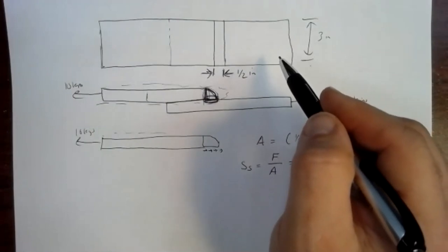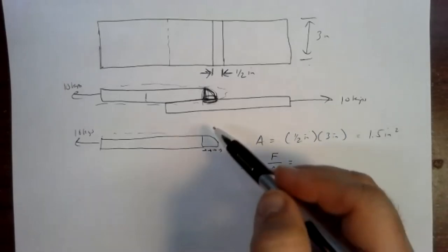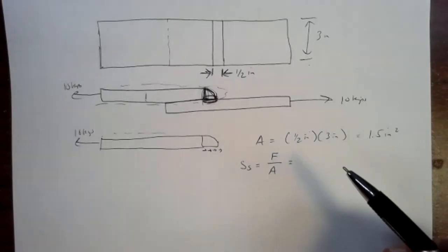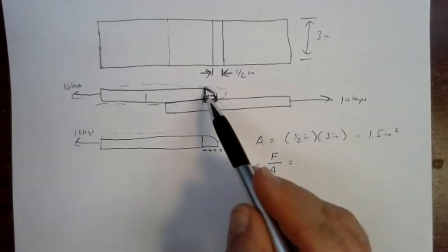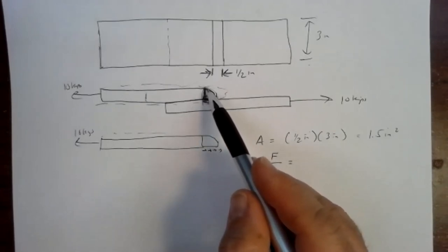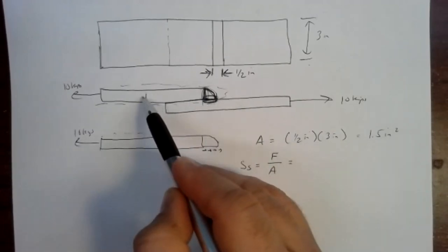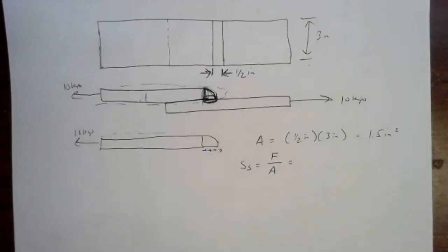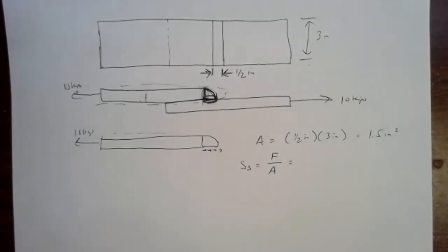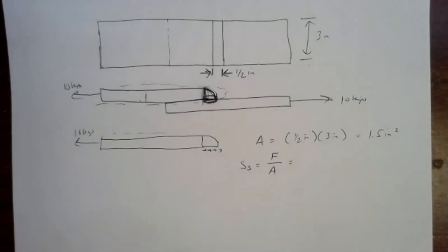That could be done too, but I'm going to assume that that is not going to be the critical factor here in this one. But these sizes do all come into play when you design a welded joint. You do have to worry about which could max out first, and typically we get around it by making sure that the stresses here tend to stay lower than the stresses out here, so that the base material will tend to max out first.